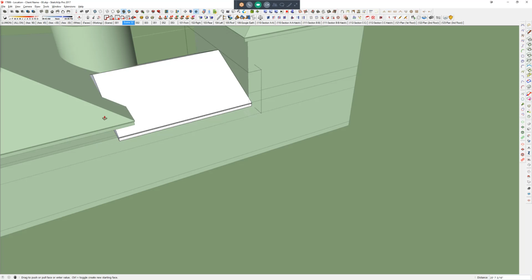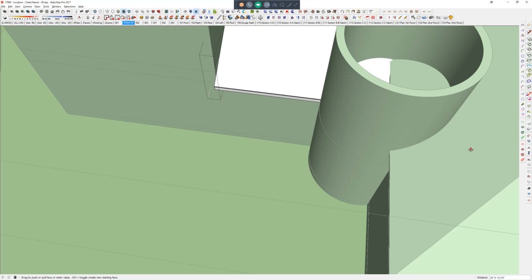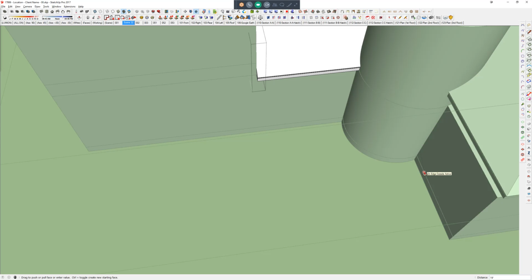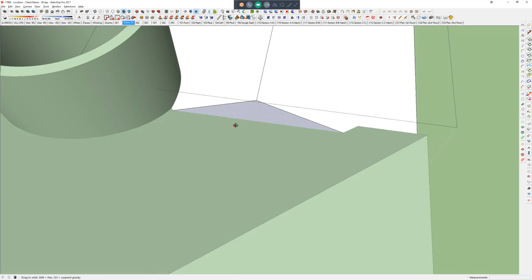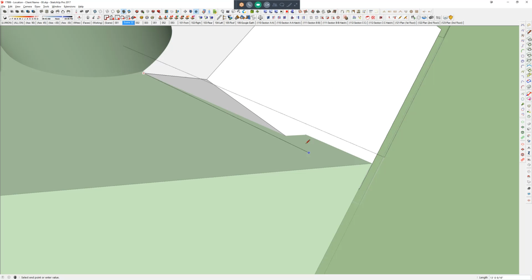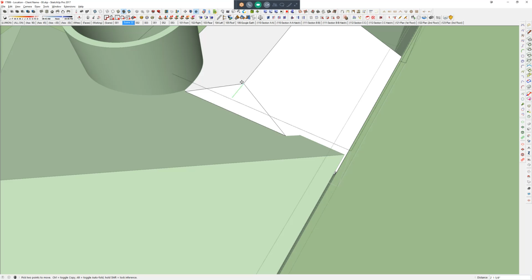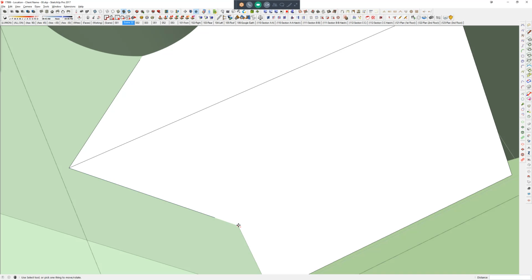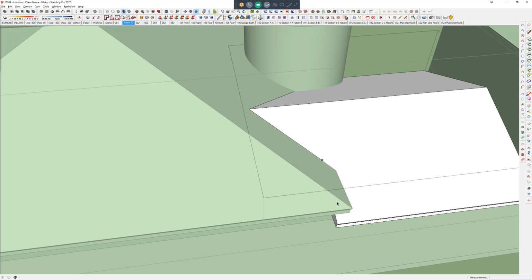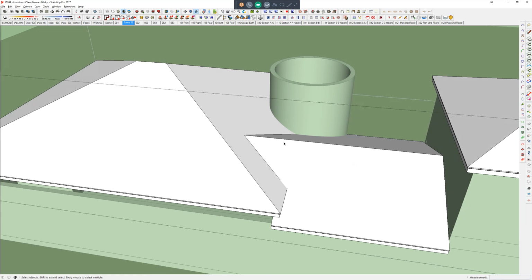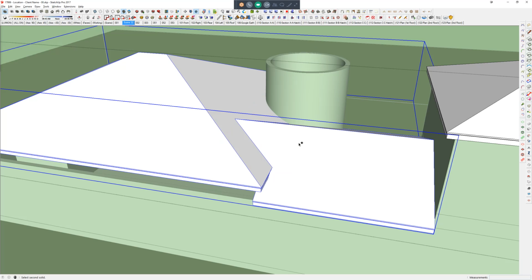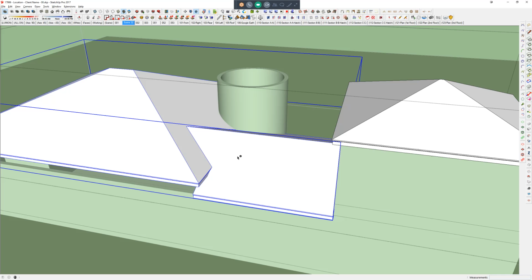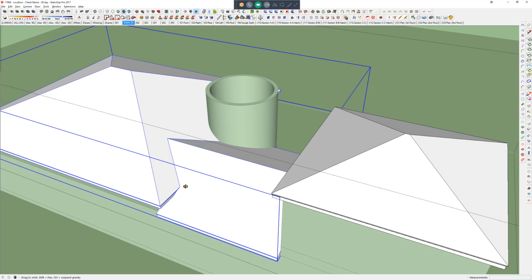And then just like before, I'll hit the face of this wall, which is where my gable wants to stop. And then you can see I can just draw that same line I drew before and do this. And again, I'm still missing this line, but there's going to be a couple of issues now. So I know that this is the roof that I want, and so I can use my solid commands and I'll join these two. But you'll see that I will have one other issue, because that gets rid of that line there.